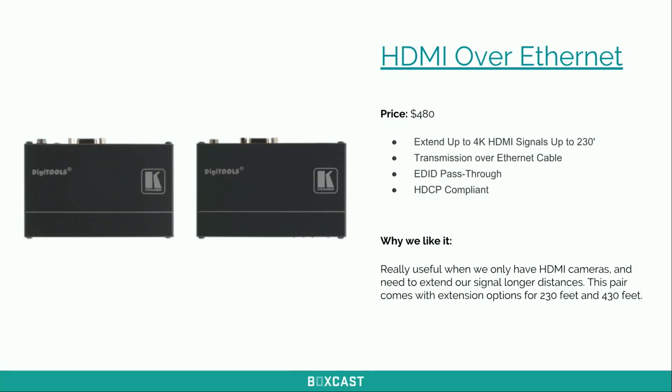It has transmission over, obviously, an Ethernet cable. The main key thing, if you're going to buy some of these, is you want to make sure it has EDID pass-through and is HDCP compliant. If it doesn't have that, it could go into your switcher, or whatever you plug it into, and it could simply not work because it thinks you're stealing data. Yeah, right. But let's show you what one of those looks like.